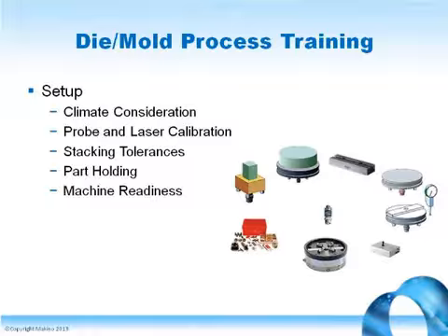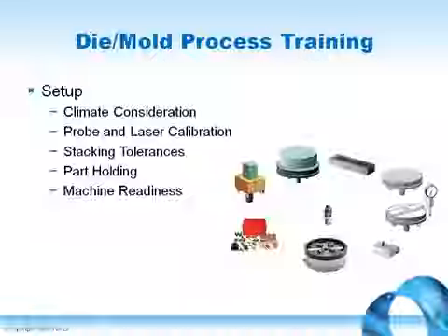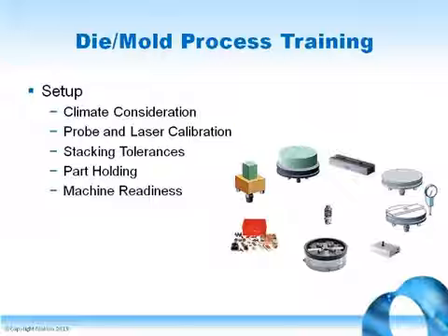Machine readiness. Check way oil levels, if the machine requires. Validate spindle cooling system is filled sufficiently. Inspect all coolant levels to satisfy cutting condition. Provide coolant or air oil mist if used. Verify the grease system is working properly and is full.